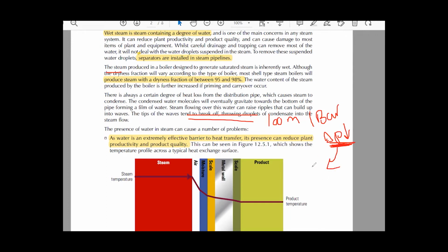When the pressure of the steam is reduced, it condenses, and the water is entrained in the steam, so I have to put in a steam trap or a separator to remove this condensate, to avoid damage such as water hammering or corrosion or many other results that can damage my steam system.